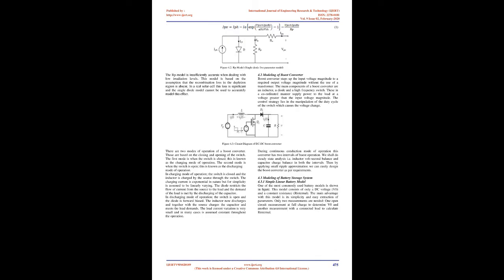2.3.3 Impact of temperature on the VI characteristic curve of a photovoltaic module. Module temperature affects the output voltage inversely. Higher module temperatures will reduce the voltage by 0.04 to 0.1 volts for every 1 Celsius degree rise in temperature, 0.04 V/°C to 0.1 V/°C. In Fahrenheit degrees, the voltage loss is from 0.022 to 0.056 volts per degree of temperature rise.